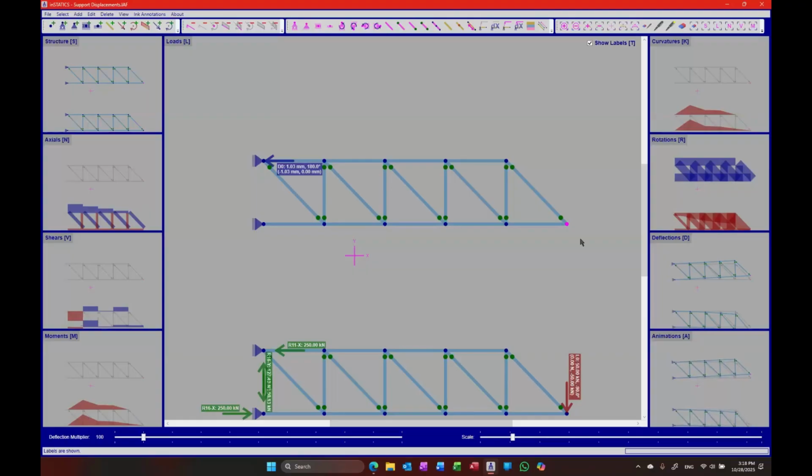Good. Think about it like this. Remember, we talked about deformation being linear, right? So rotations become slopes. So I move this. You can see that it's going to pivot around this, correct? Because I'm going to pull this, this is going to move up. So we know that whatever this thing is going to rotate, it's going to rotate as a whole body.